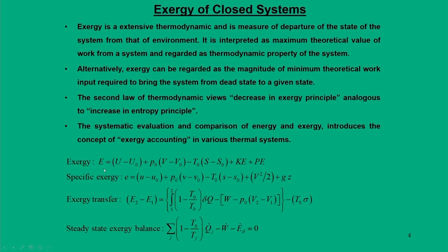In our previous lecture, we derived the expressions for exergy. Any system at an arbitrary initial state with internal energy U, volume V, entropy S, with certain kinetic energy and potential energy, has an exergy which can be considered with respect to the environment in the dead state, that is, when the system moves from its arbitrary state to the dead state.